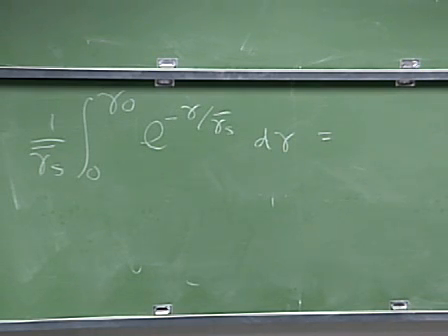So gamma S bar is the average value of gamma S. Remember, gamma S changes randomly over time, following a Rayleigh distribution. To be precise, the amplitude of the signal follows a Rayleigh distribution, so the power of the signal follows the exponential distribution. And so gamma S itself follows the exponential distribution. It changes randomly over time, and gamma S bar is the average of the distribution.